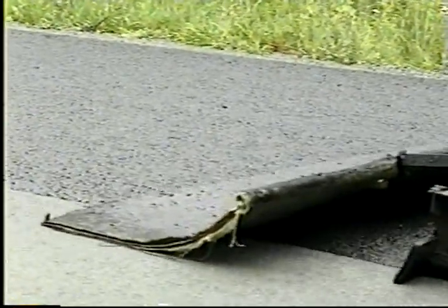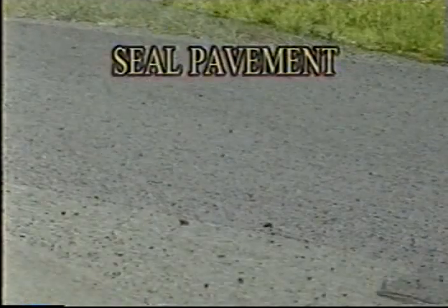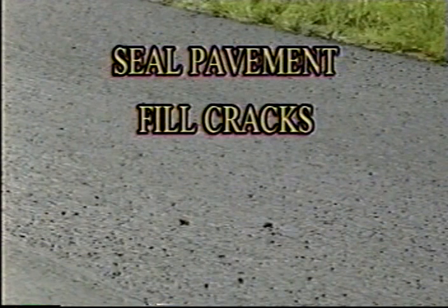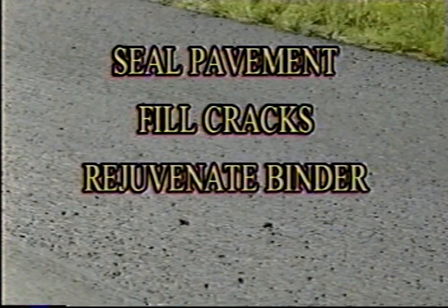Seals are designed to provide one or more of the following benefits: to seal the pavement, preventing the intrusion of air and moisture, to fill small cracks and voids, to rejuvenate an oxidized binder, and to provide a new wearing surface.